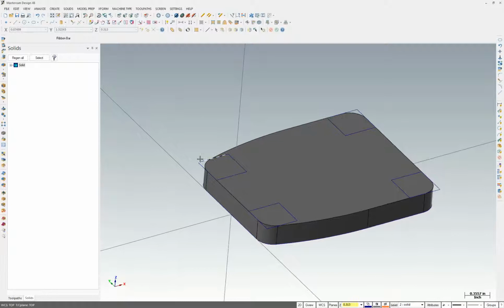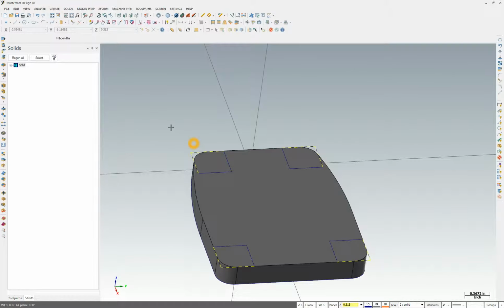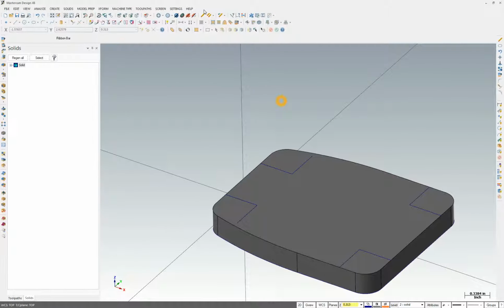Now let's delete the lines we don't need, which are the outer lines of all 4 of these squares. Just go through and select the items you need, and delete them off. Now we're going to extend all the lines we have. It's under your trim icon, and we're going to click this guy, and we're going to go value of 1/4 of an inch, and we're going to extend all these lines.